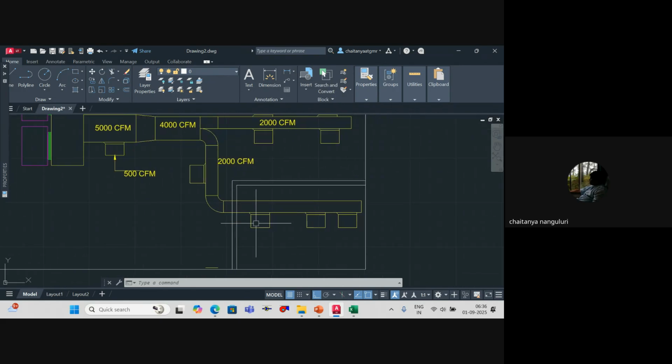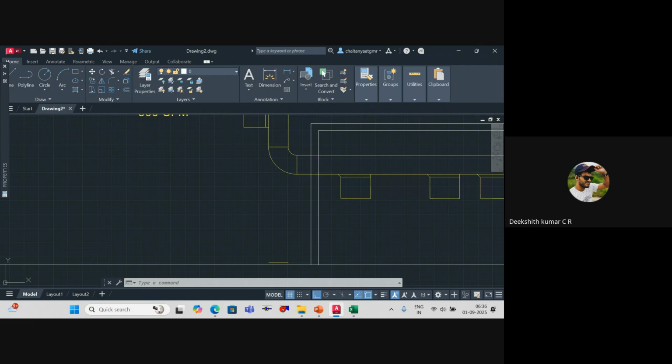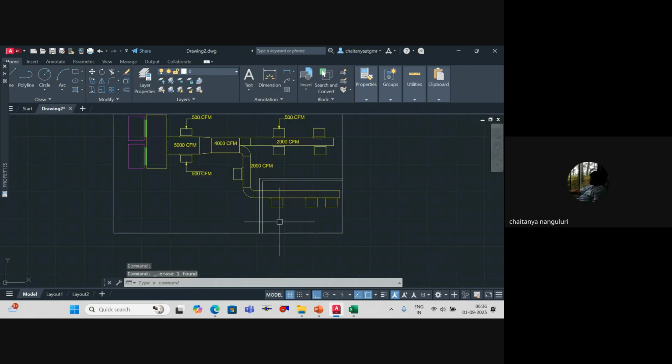So whenever there's a fire in batteries, do you want your entire room to be propagated or not? You don't want it, right? So let the accident be contained in that particular room for at least 2 hours, as per fire norm requirements. Generally 120 minutes.